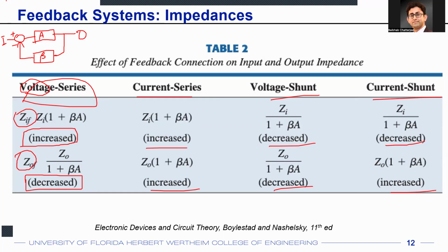So you can think of it that you're reducing the voltage at the output, increasing at the input. According to Ohm's law, voltage over current, that's your impedance. So you're taking away voltage from the output, so your impedance will be decreased. And you're putting voltage back at the input side, so your impedance is increasing because now you have more voltage at the input side, assuming that the currents are all the same, right? So this is a quick way to remember.